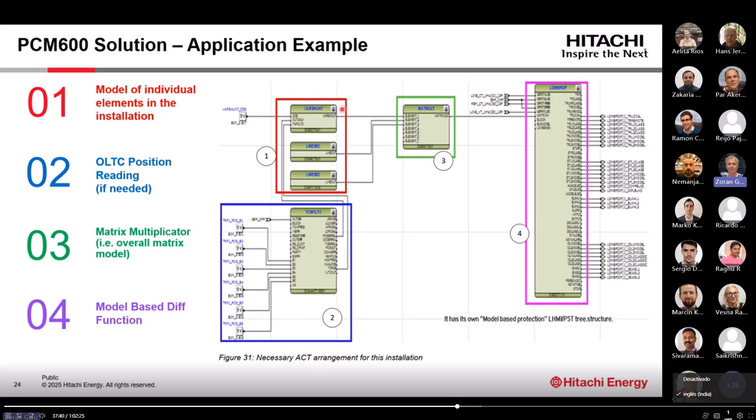And when you energize it, we practically take this out of the calculation automatically. In this way, you can dynamically take them in and out. Line sections, currently you cannot take out of service because they are physically large over larger distance. Until now, I don't know any application where you can easily take the line section out of service.